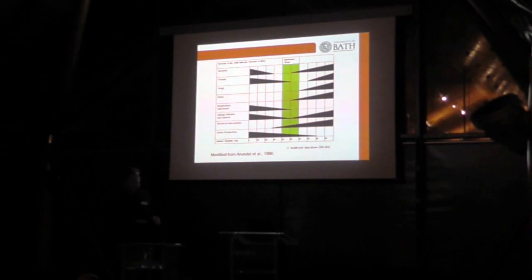So that's a quick table just to explain why it's important to get stable relative humidity in the building. So he shows here that with a high relative humidity, and what I call relative humidity is the vapor concentration on the saturation vapor concentration, so it's a percentage. So here, at high relative humidity, you can see that there's an increase in microorganisms like dust mites, viruses, bacteria, and also at low relative humidity you get trouble with respiratory infections, allergies, asthma. I think asthma is probably one of the main concerns in England because it's the world leading country of people suffering from asthma, 15% of the population. So there's an optimum zone that has been identified between 40 and 60% relative humidity.